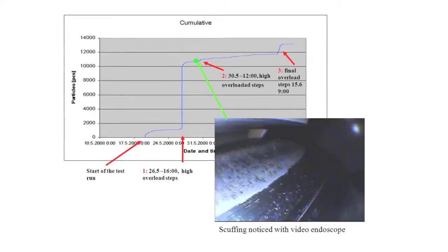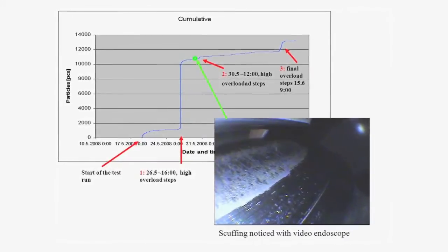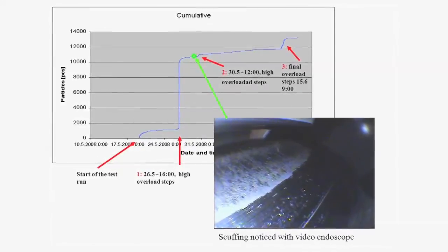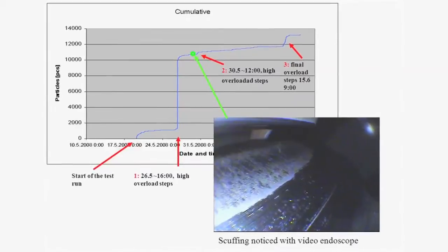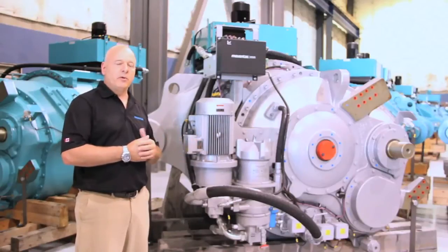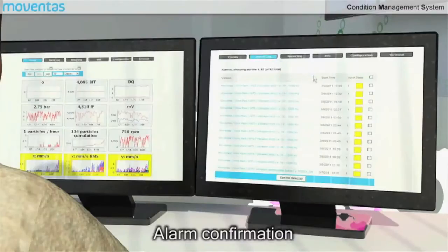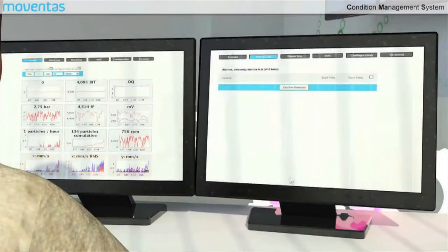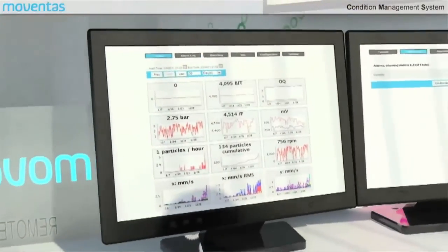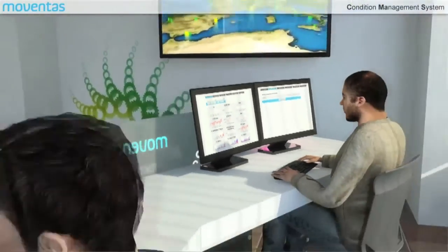The particle counter is able to count particles of debris as they pass through the gearbox, and obviously as things wear out, we're starting to generate more debris. But there again, we're just monitoring a defect. The chemical sensor that we're using is also able to monitor the water content. This sensor is monitoring all the time, and we're able to see the changes in that free water condition.